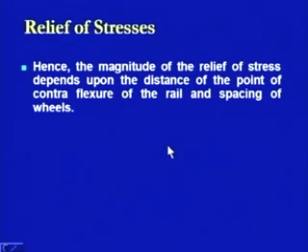So, here what we found is the magnitude of relief of stress depends upon the distance of the point of contraflexure of the rail and spacing of wheels. This is what becomes the conclusion as far as the relief of stresses is concerned.